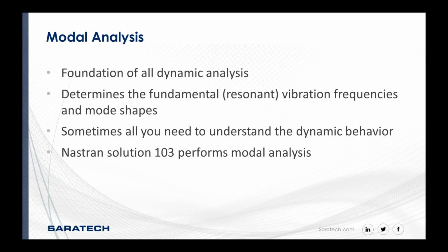Our modal analysis is the foundation for all dynamic analysis. So if you are doing any sort of dynamic analysis, please start with a modal analysis. It'll give you information about your structure before you even step into the next level. Doing modal analysis, we'll find out the resonant frequencies of the structure and also the mode shapes.